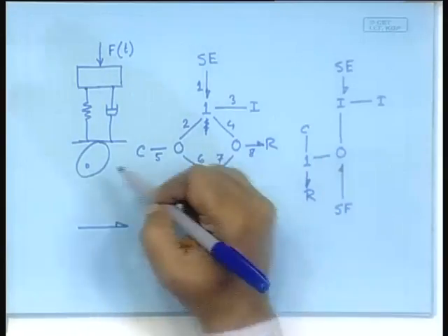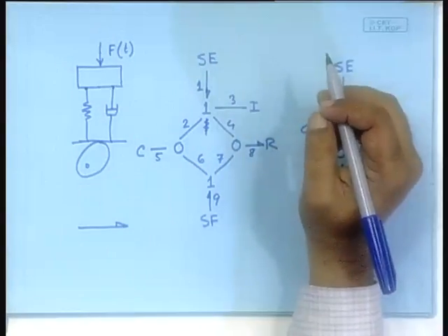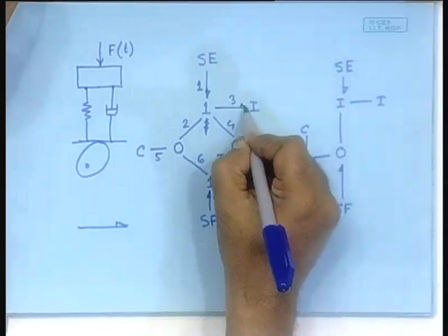Now, the inductive and the capacitive elements do not really absorb or generate power. For some time they absorb power, for other parts of the time they give it out. In that case we still have to assign one direction as positive, and the convention is that we denote as positive the power that is absorbed by that element. So, our power direction will be like this.